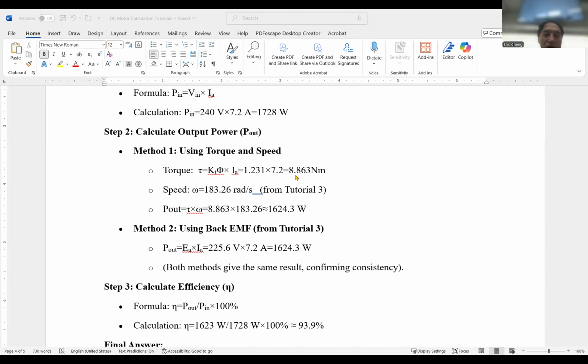So for this question, we have a PWM driver with 120 volt DC, switching at 20 kHz, and a motor armature resistance of 2 milliohm, and the current is 50 amp. Now they just ignore the resistance for the calculation. That makes the PWM calculation much easier.